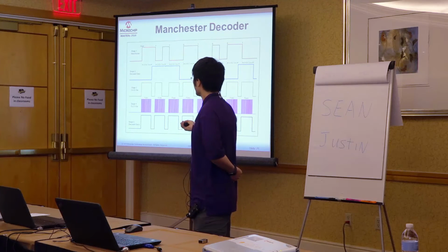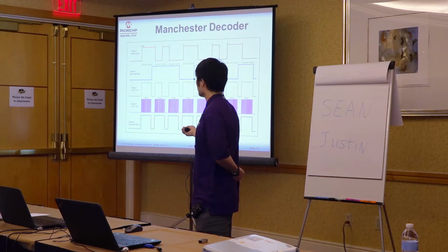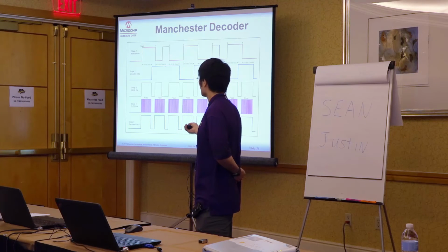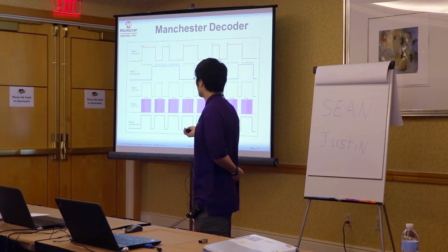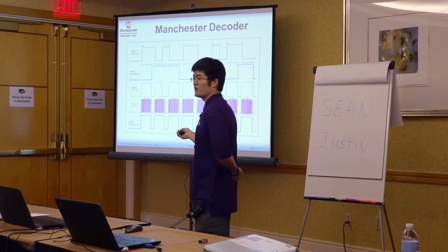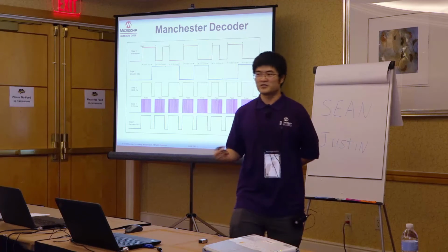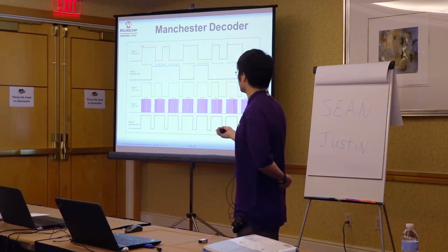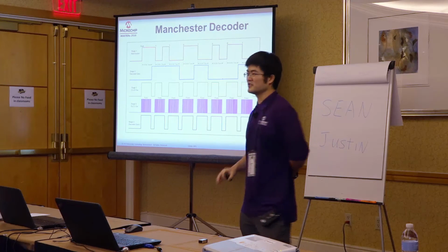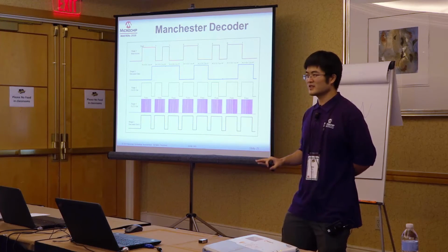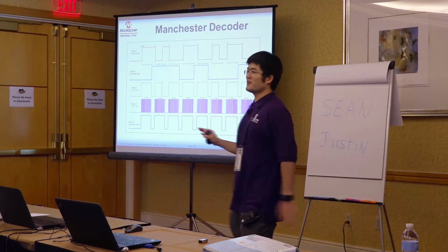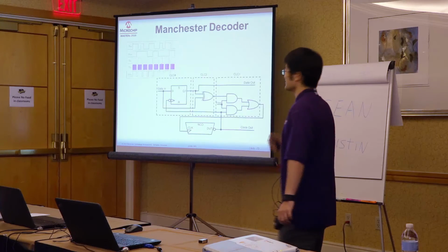So naturally, whenever this one is available and this one is still counting, I will output a 1. When this one got chopped off because of the data pattern, a 1 followed by a 1 here, but my NCO is still counting, I will just keep my output as 1 until the counter counts down to 0, or the value it is set to. That way, I can extend those unfortunate cases into a 75% duty cycle. Make sense? All right, so those waveforms might be a little bit convoluted, but once you see this, it might become clear, I hope.